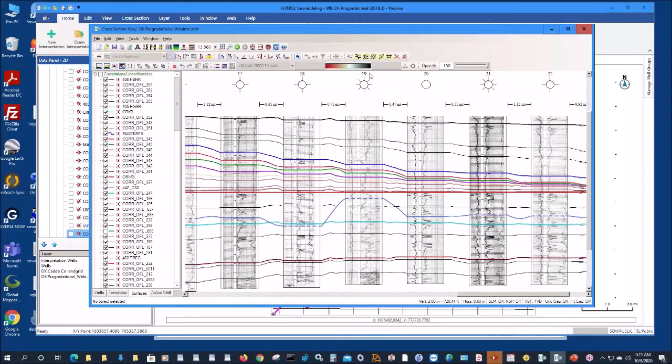What I need to do now is go ahead and apply the conformance tool. There are your 5 geomodeling tools up here: fault, offset, conformance, unconformity, trimming, and fault and unconformity networking here. I'm going to apply conformance and hit the check mark to turn it on. And what we should see is, there we go, the blue surface, CS2, conforming to 247. So that's how conformance works in general, okay?